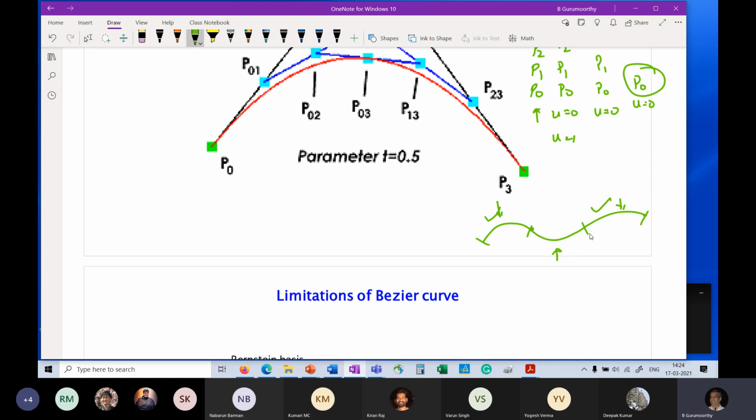The endpoints are fixed, right? Therefore, they have no choice here, which is not too bad, I would say. So let me call this P2,0, and I'll call this P2,3. Let's assume that these are all cubic curves. So n plus 1 is 4, n is equal to 3. Now, clearly, to get a cubic curve, the designer has the freedom to prescribe 2 more points. You need 4 control points to define the Bezier curve in the middle.